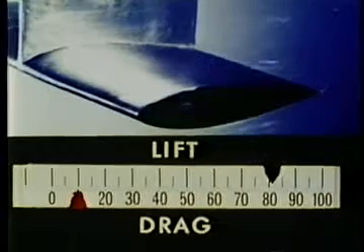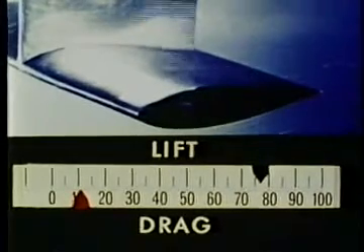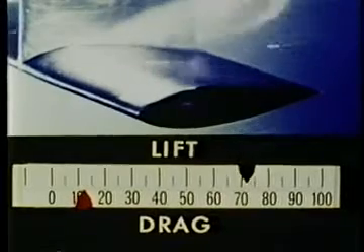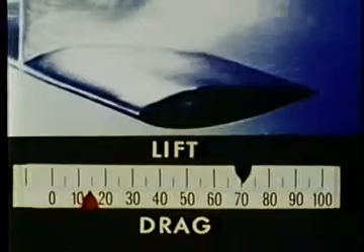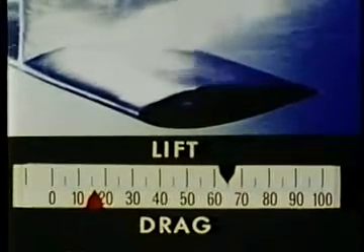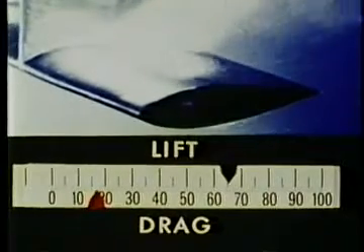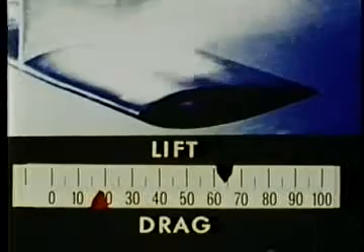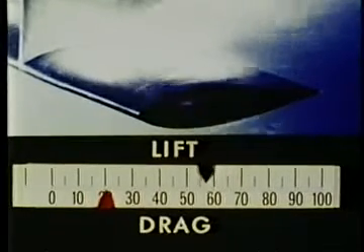At first, there is no appreciable change in either force. As cavitation develops, lift decreases and drag rises. You can see from the force balances that the flow is quite unsteady. When we lower the pressure further and allow cavitation to spread, the lift decreases further and the drag continues to rise.